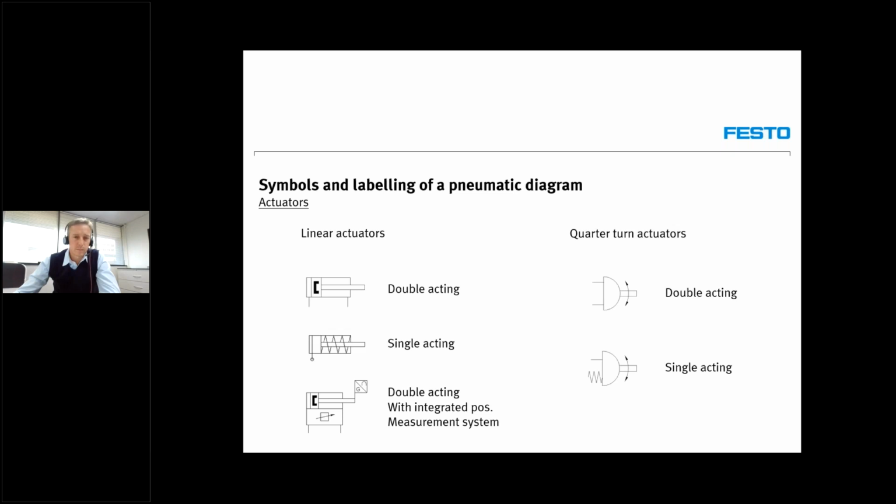So in essence, when you have a vast quantity of water coming through, and maybe the little knurled nut isn't really the right mechanism for you, then you can of course use simple robust solenoid valves to open and close on a time basis. You of course can put a very crude ball valve at the bottom end to open and close it if that sort of suffices for you.